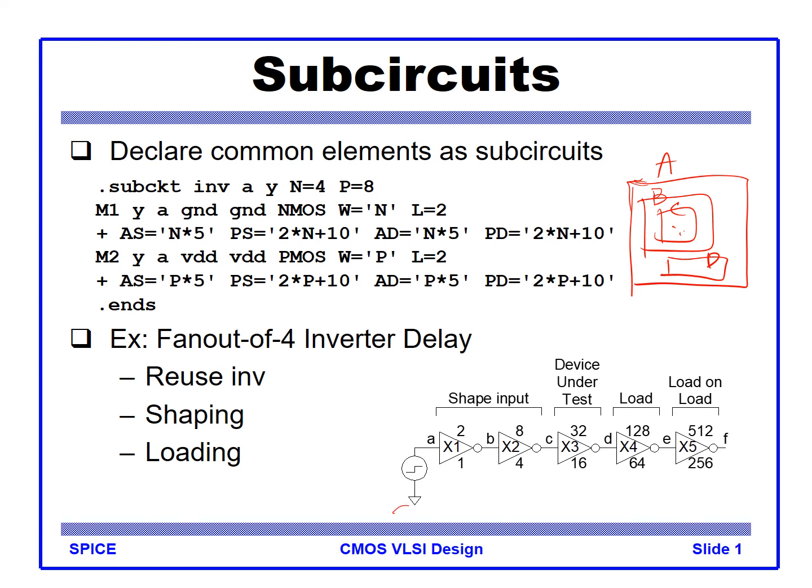For example, for this kind of circuit, each inverter has a PMOS and NMOS inside. So this kind of instance is the sub-circuit. We define that inverter with a sub-circuit definition, starting with the .subckt. The sub-circuit needs to have an input and output. So the input port information is here, and this is the property we want to pass on to the sub-circuit.